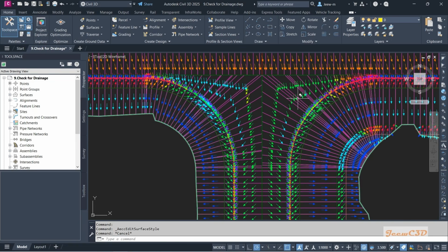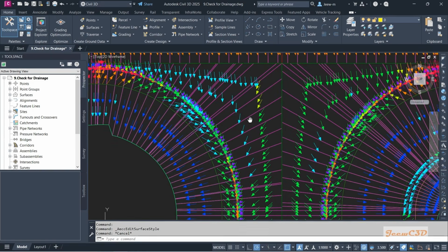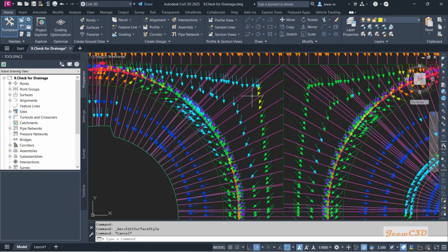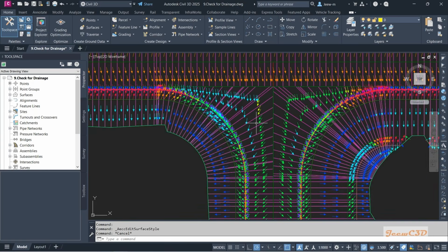This is also water going away toward this area, right? That is one way. If any arrow has a very small angle, or it is not going to drain away from the corridor, that should be a location to think about, right? So you have to make sure that it is not going to happen.